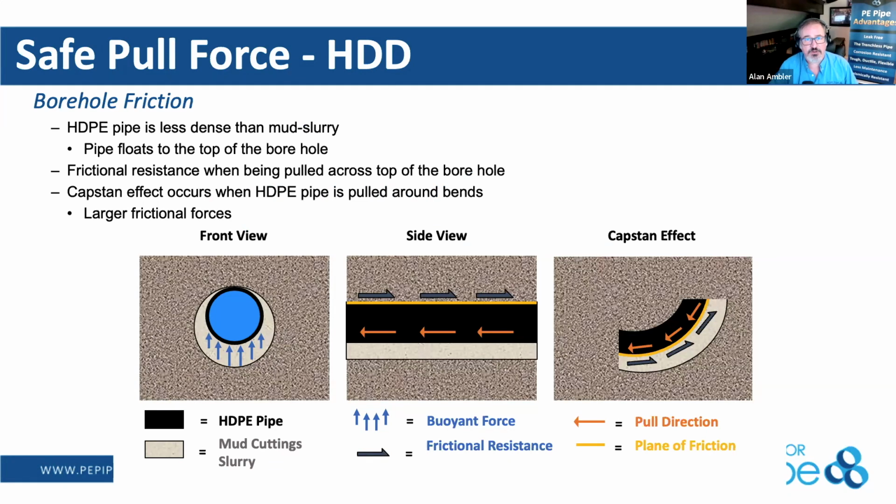What we are looking for from a design analysis is friction along that bend when we achieve curvature underneath whatever it is we're trying to clear at depth, and then we come back out to achieve that curvature. HDPE, as its density is lower than water, will float. Sometimes we will ballast that pipe by putting water inside the pipe to lower those friction forces as we go through.